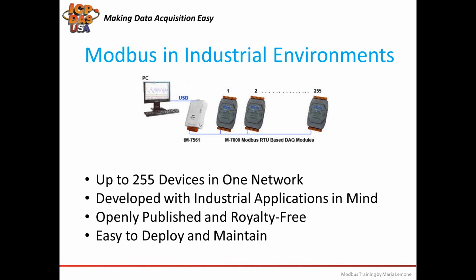If you are communicating through several walls, it depends on the kind of wall. If it's like a steel wall, then the communication signal may not go through at all. But if it's just regular office walls, then it's similar to Wi-Fi. It does operate over the same 2.4 gigahertz band, so the signal can go through. We've tested it, for example, at different offices, and it does go through. And yes, based on your building or your environment, you may want to add more repeaters or devices in your network.